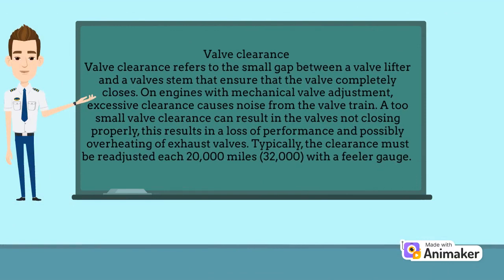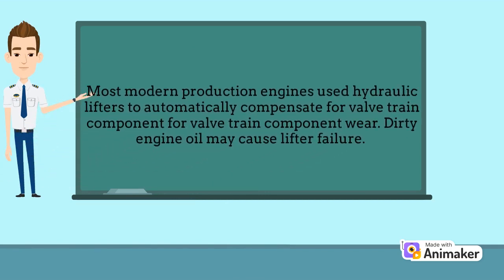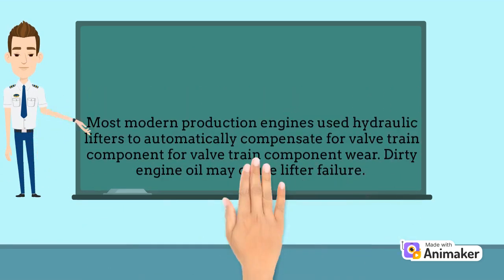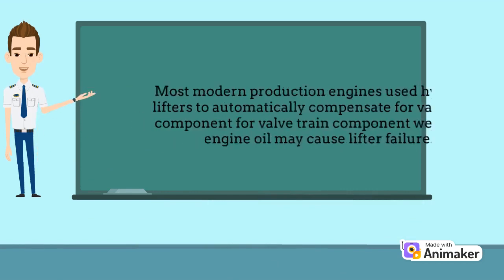Valve clearance. Valve clearance refers to the small gap between a valve lifter and a valve stem that ensures that the valve completely closes. On engines with mechanical valve adjustment, excessive clearance causes noise from the valves not closing properly. This results in a loss of performance and possibly overheating of exhaust valves. Typically, the clearance must be readjusted each 20,000 miles, 32,000 kilometers, with a feeler gauge. Most modern production engines use hydraulic lifters to automatically compensate for valve train component wear. Dirty engine oil may cause lifter failure.